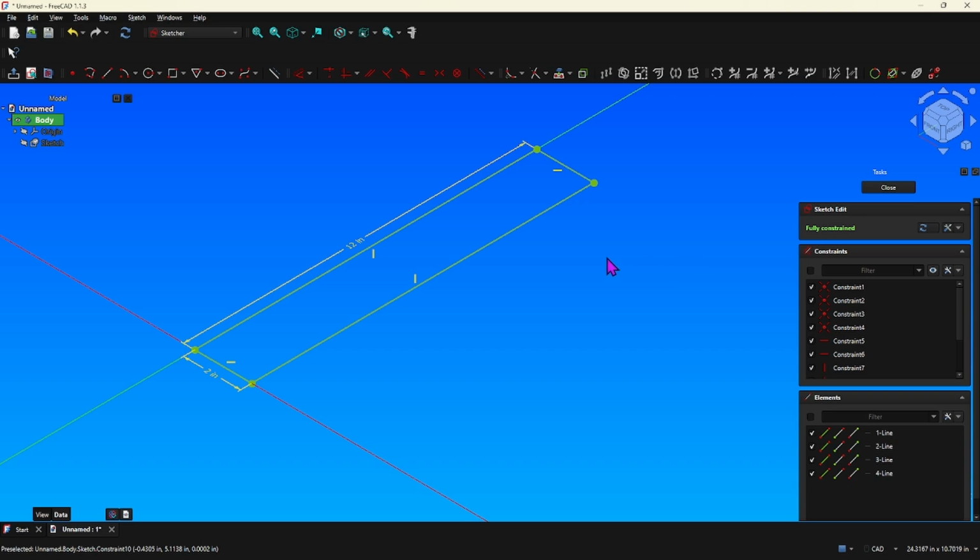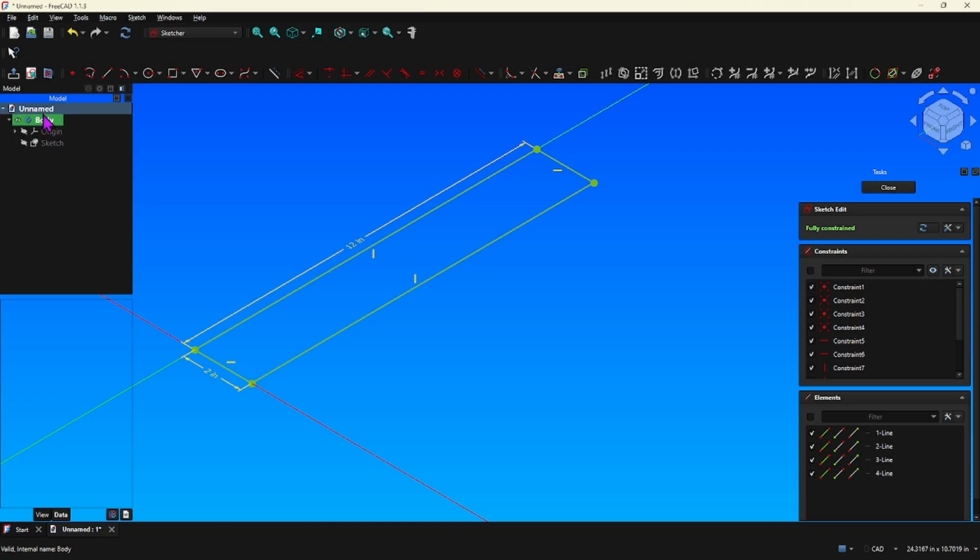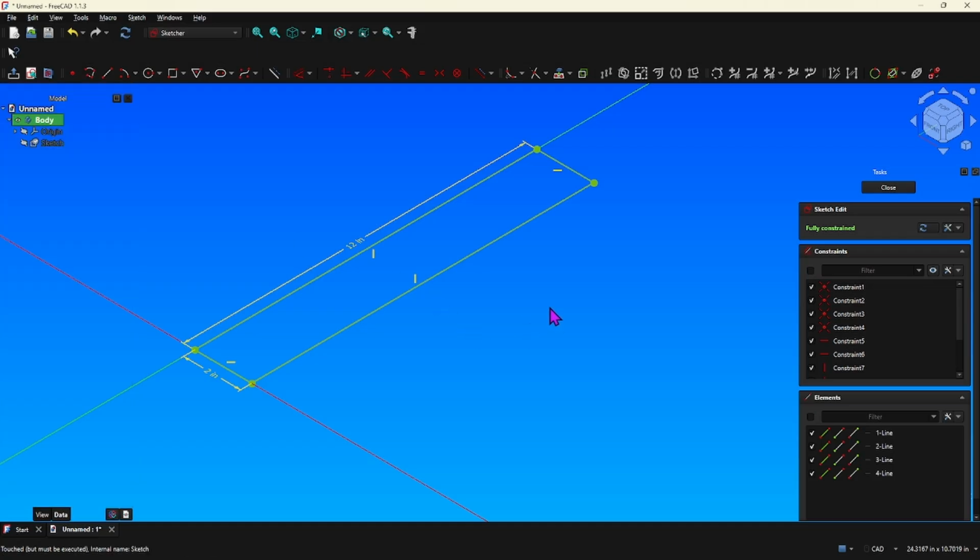That's why I wanted to do this video, to stress using constraints and ensuring that your sketches are fully constrained before you give them thickness or pad them or do a pocket. Down the road, when you have multiple bodies and parts and pieces going together, if they're not fully constrained and there's other parts referenced to your body items, it can throw your dimensions off.